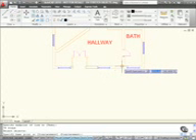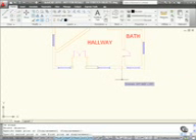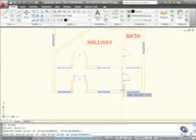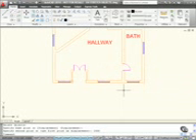So, internal corner again, that one there, left click, drag vertically downwards down my polar tracking line like so. I type in 2000, as I did before, and press enter, and everything stretches. Notice I avoided those arcs. When you stretch arcs, they look messy. So make sure you go round them with a crossing polygon selection.